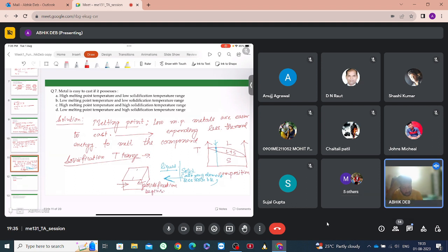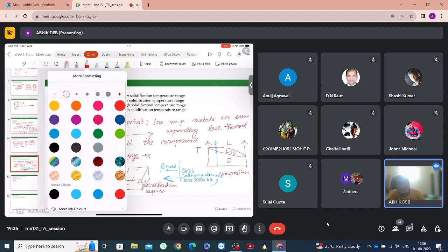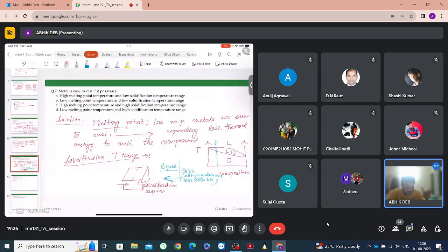then at the center it will have a totally different composition. At the sides, it will be the initial composition, like 30% nickel and 70% chromium. But at the center, due to this process, it will be much more nickel than chromium, or much more of the alloying element will start pouring. Basically this alloying element will start moving from the faces from which the solidification starts towards the center. So it will result in a heterogeneous structure.